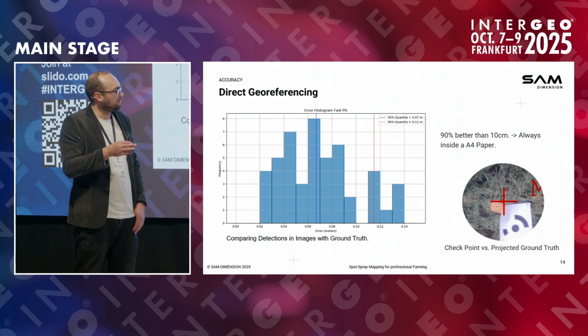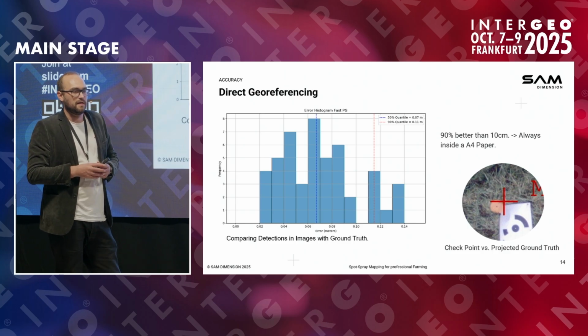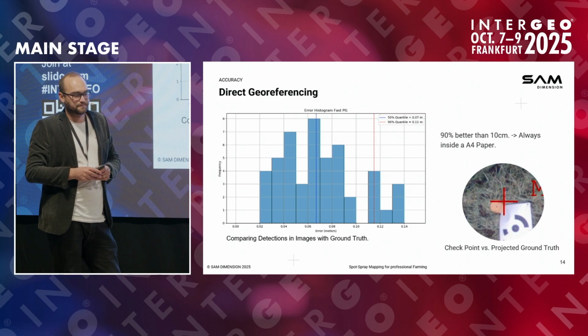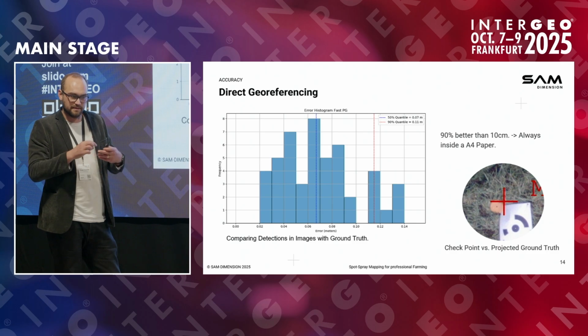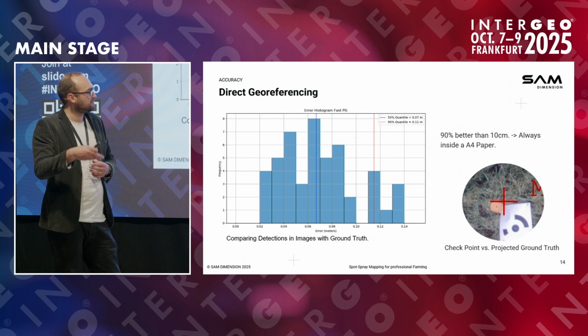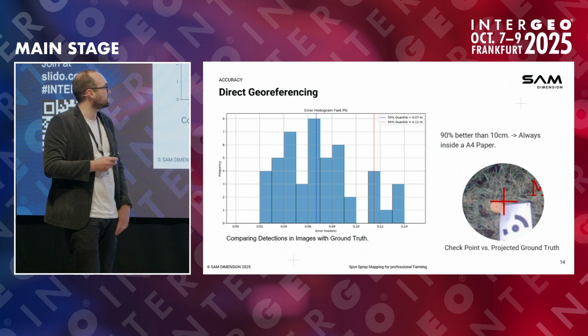That is a bit contradictory to normal photogrammetry, like with your DJI and with 80% overlap, basically with only one camera, where you can achieve an accuracy in the millimeter range, like your pixels. But we designed our system to be faster and go only for the resolution, but not for the accuracy.